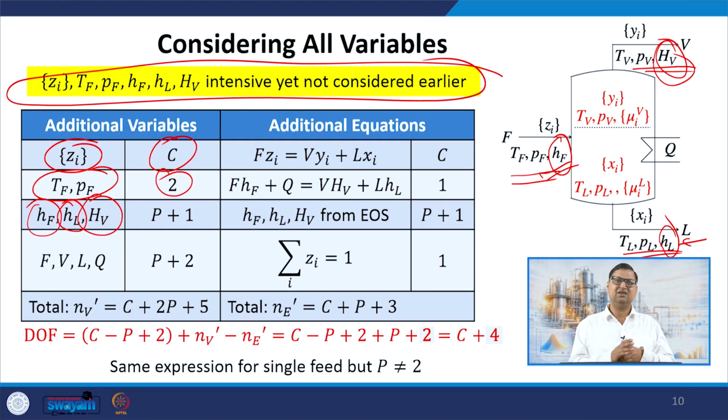What we are saying here is that the feed carries some energy into the system, liquid takes away some energy along with it, vapor takes away some energy along with it, and we are supplying some heat, and the energy being carried is represented by the enthalpies. And now we have 3 molar flow rates and also a net heat supplied or taken out from the system. It depends whether we are taking away heat or giving heat depending on the requirement, right.